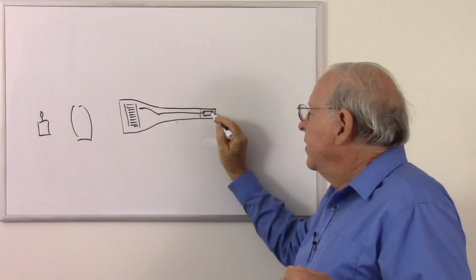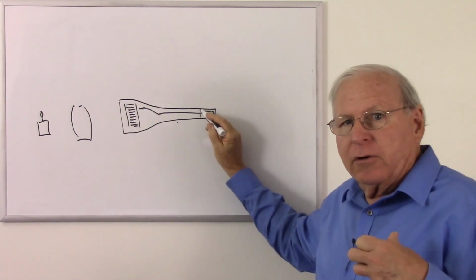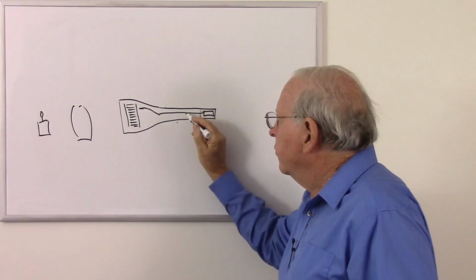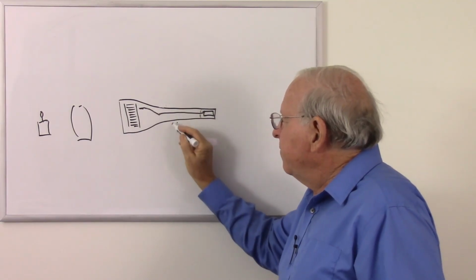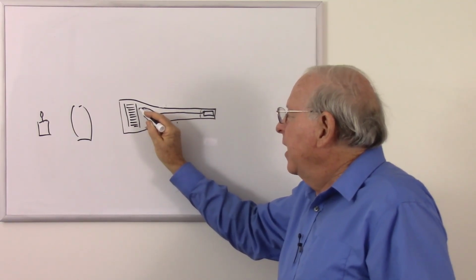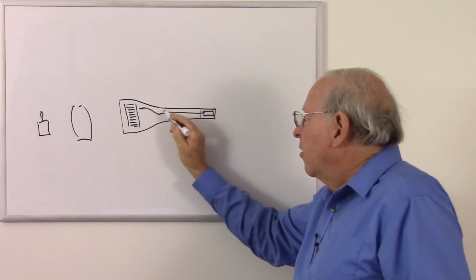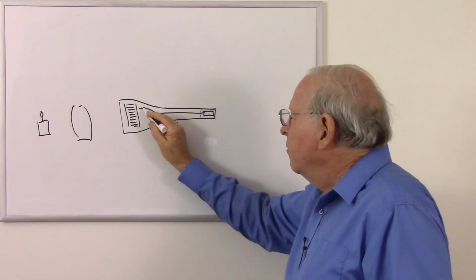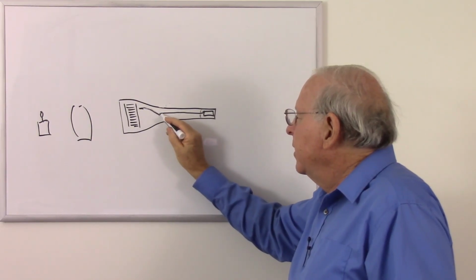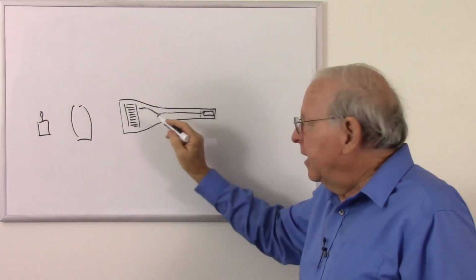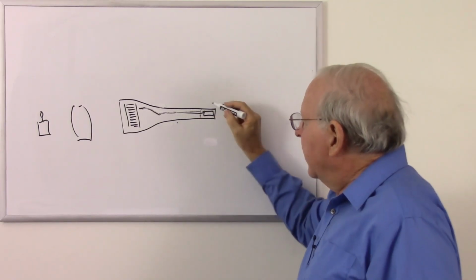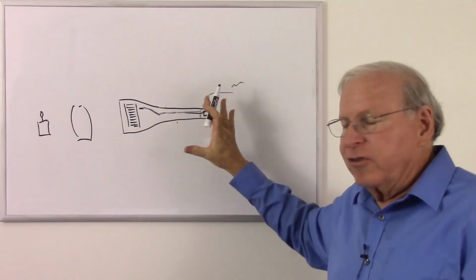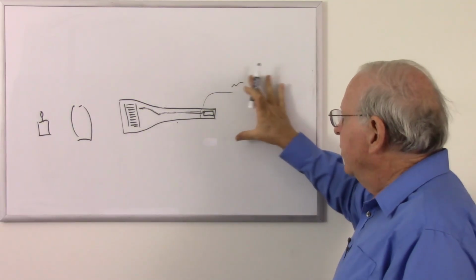So these negatively charged electrons, you would think, would go to this positively charged grid here. But instead, their momentum carries them through. Then the magnetic fields deflect it, come in straight, and those electrons that come back straight are attracted to this positive charge here. So they follow the same path, basically, back because of the magnetic fields, and are absorbed by that positive grid, and that gives us voltages that we can use to send to the CRT to recreate the image.